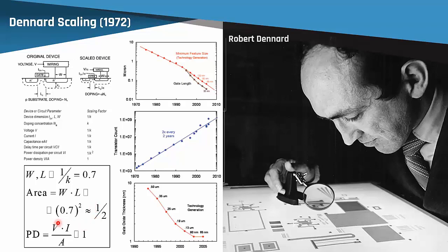But the important point that Dennard made, which has become more prominently important in the last number of years, is that he also showed, and we all learned this except for Eliana, Victor and Mark, who are going to be learning it this semester, that the power density stays constant. And that's maybe the most important thing here, or at least it became the most important thing. So despite the fact that we keep making these transistors smaller and smaller, in the same amount of area we can pack double the amount of transistors every year. And remember, in 10 years, that's 1,000 times more, right? In 20 years, that's 1,000,000 times more. But we still get the same heat dissipation in that type of area.